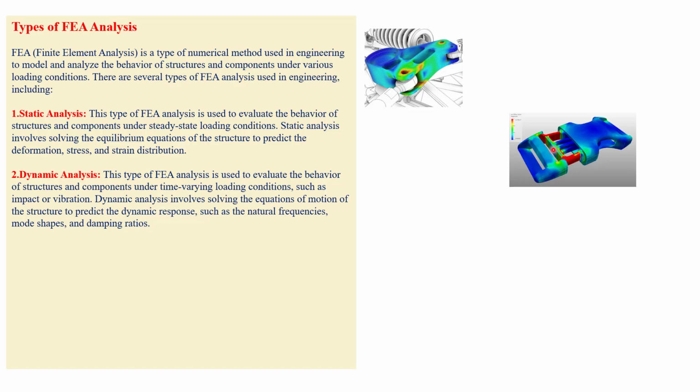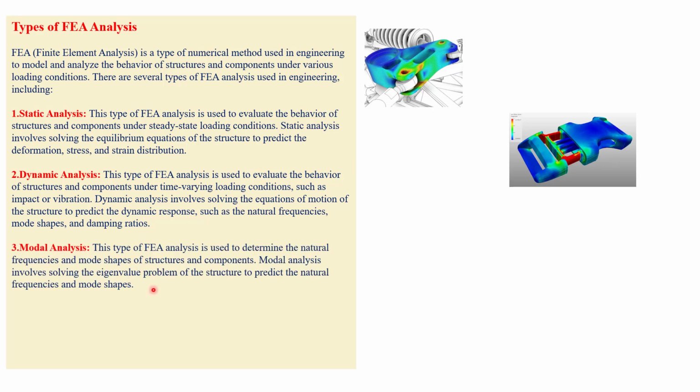For example, if you consider this one, here we can see nonlinear analysis in the form of dynamic analysis. If we would like to cross verify, we can cross verify the natural frequencies of this component and its modal analysis, so that we can predict how it is behaving and proceed further. The next one is modal analysis, where we extract the eigenvalues and predict the natural frequencies and mode shapes of the components. It's very important in current automotive work also.